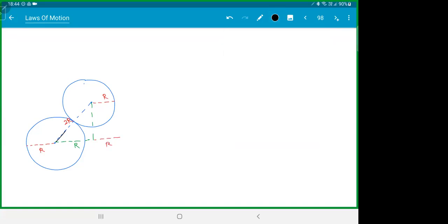So if you look at this triangle here, this angle is theta. We get cos theta is equal to half. Theta is 60 degrees. Is that making sense? It is given the horizontal distance is 3r. The distance between center to center is 2r. This distance is radius. This is also radius. So this should be also radius. Please check this out. The same way you can actually find for the upper one also.